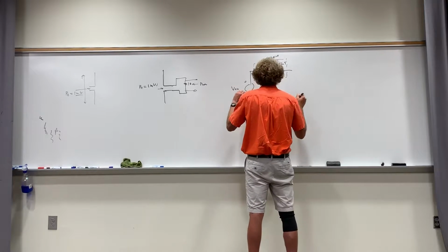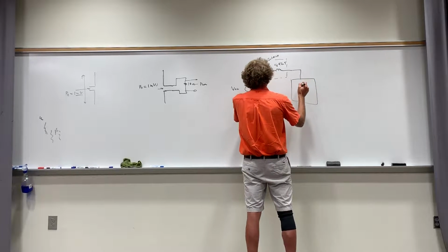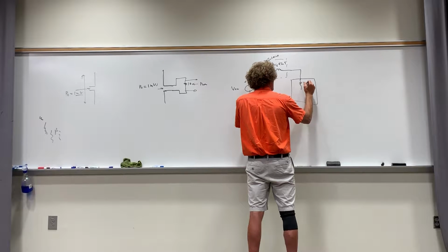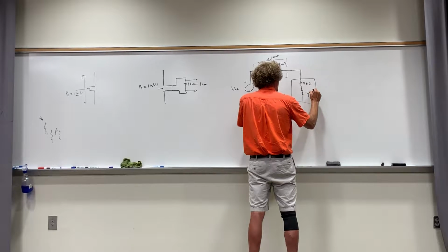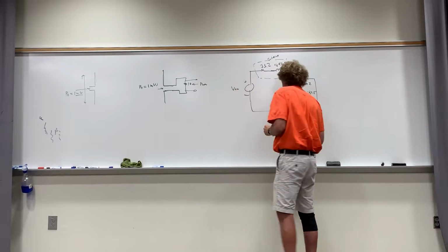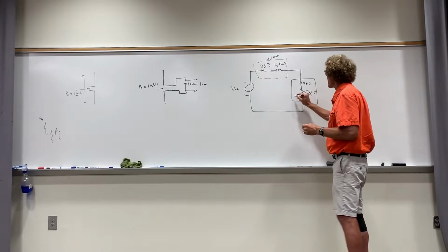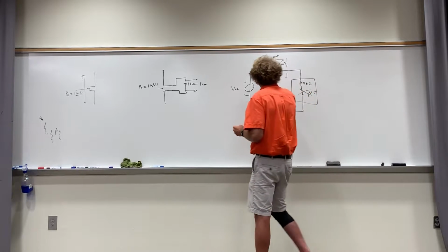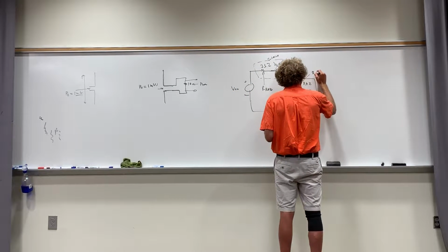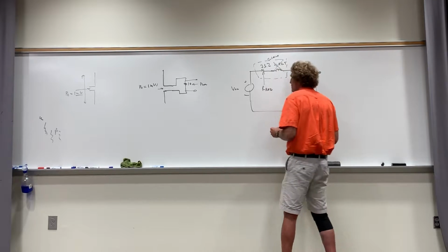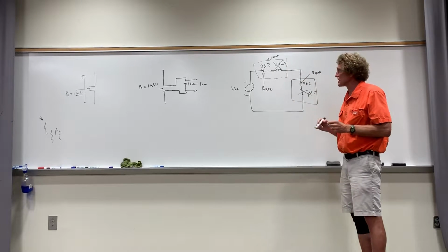Now, when they talk about P received as 1 milliwatt, they're saying if this was into a matched load, and you remember a matched load would have the same real component, 73.2, but the reactive portion would be minus j42.5, so it would cancel. This would allow the maximum power to be received. Do you all remember this, class? Now what I'm going to do is just get rid of this imaginary part and simply leave this and call it R rad, the radiation resistance of the antenna. And this is assumed the configuration where we're talking about a maximum received power of 1 milliwatt. It's in this configuration. Do you follow me?